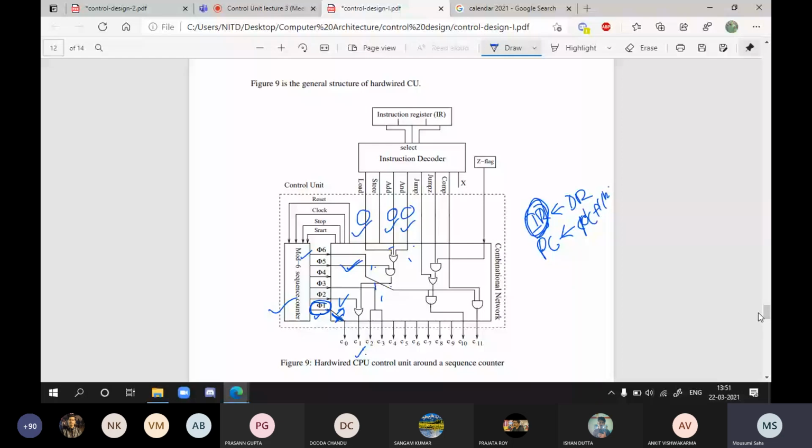These two operations we define with the help of the control signals C0, C1, C2, and C3. And for all instructions, these operations should be done. So directly it can give the signals C2 and C3. It doesn't depend on anything; we never use any gate here. That means it doesn't depend on any instruction. This is common for all the instructions. Clear?